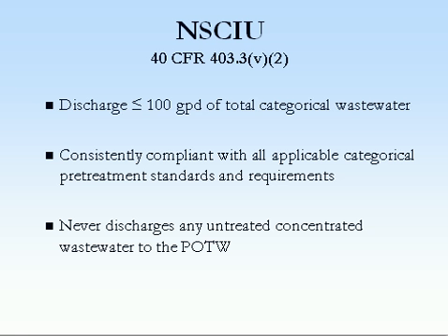In order to be considered a non-significant categorical industrial user, this slide identifies what those preconditions are that the industry must satisfy. The industry must never discharge more than 100 gallons per day of total categorical processed wastewater. The potential NSCIU must be consistently compliant with all applicable categorical pretreatment standards and requirements, and that industry must never discharge any untreated concentrated wastewater to the POTW.